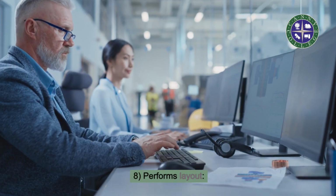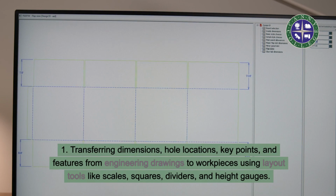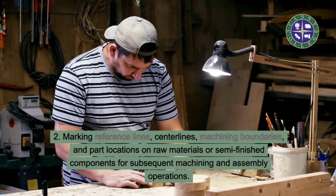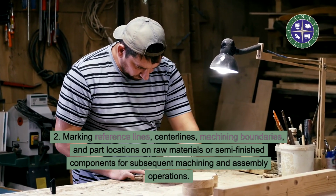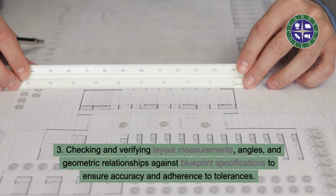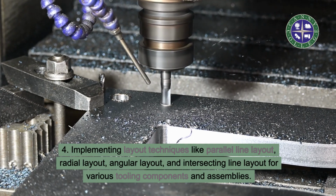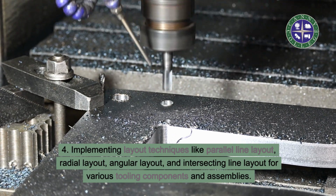8. Performs layout. 1. Transferring dimensions, hole locations, key points, and features from engineering drawings to workpieces using layout tools like scales, squares, dividers, and height gauges. 2. Marking reference lines, center lines, machining boundaries, and part locations on raw materials or semi-finished components for subsequent machining and assembly operations. 3. Checking and verifying layout measurements, angles, and geometric relationships against blueprint specifications to ensure accuracy and adherence to tolerances. 4. Implementing layout techniques like parallel line layout, radial layout, angular layout, and intersecting line layout for various tooling components and assemblies.